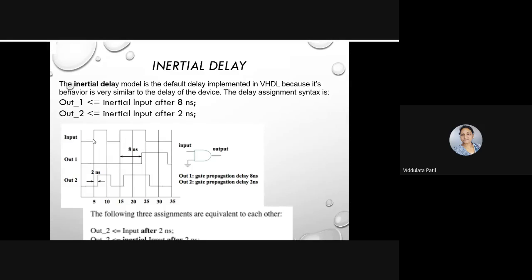Here we are saying that the output should be present after 8 nanoseconds. Whenever there is a change in the input logic level, only after 8 nanoseconds will the output be present. This is the inertial delay of 8 nanoseconds that we are introducing in the output.